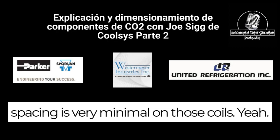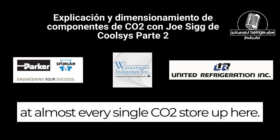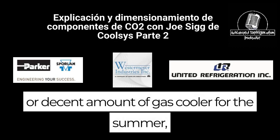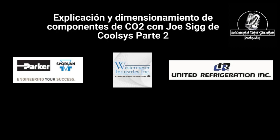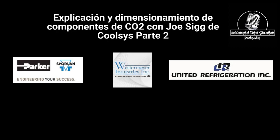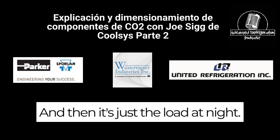So that seems to be an issue at almost every single CO2 store up here. We have a decent amount of gas cooler for the summer, but then winter hits and we are just oversized. And even when you're running static, no fans, you're still oversized? Oh yeah, big time. Really? It's the wind, and then it's just the load at night.